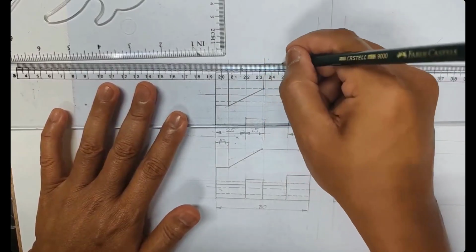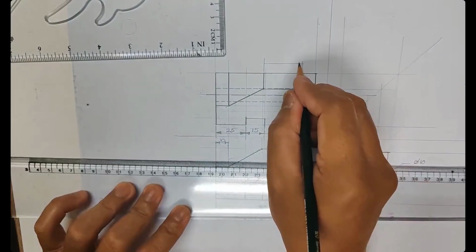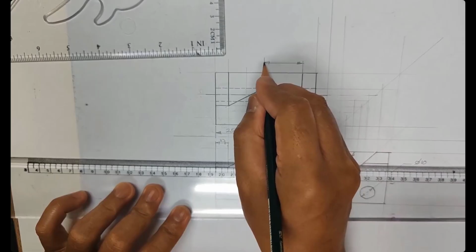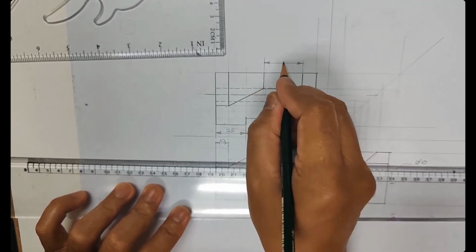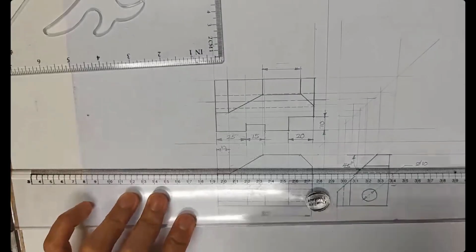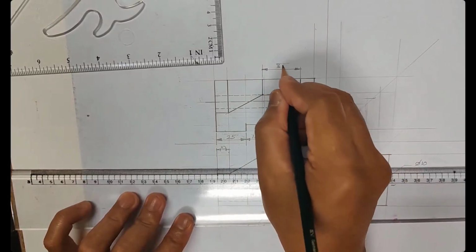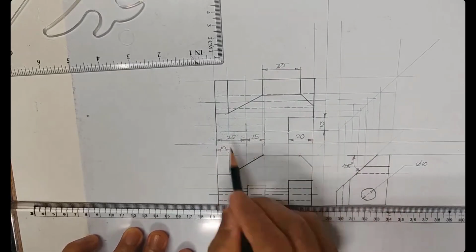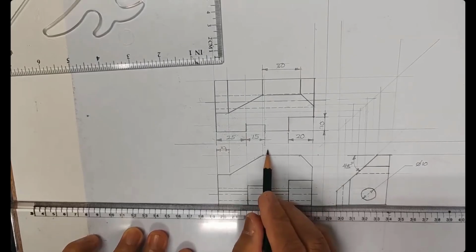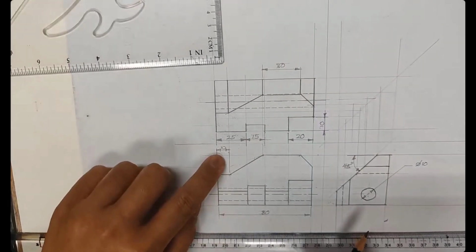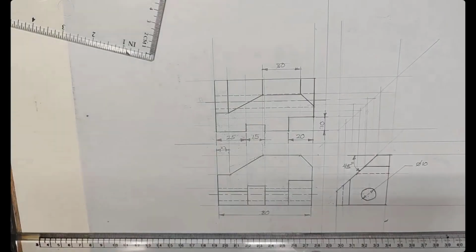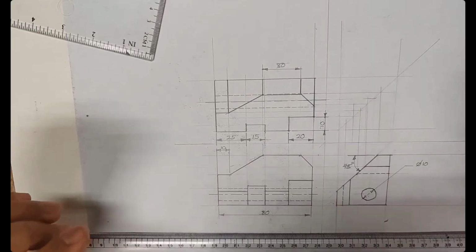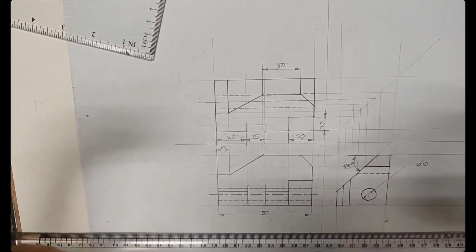Okay, so like this, 3-1, right? Arrowhead at this 3-1, do it properly. Solid line, I define it to be solid line. So here I can put the distance of 30, because I don't have space to put it here, as this area is already fully occupied with dimensions, right? So it's okay to put it there, but the 10 should be put here. If you put the 10 here, it facilitates the reader. The point is that when you distribute the dimensions, make your dimensions facilitate. Understand me? Facilitate means people can easily read your drawing.